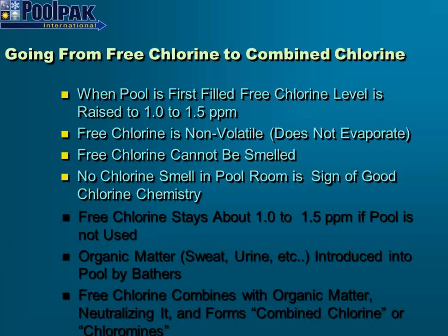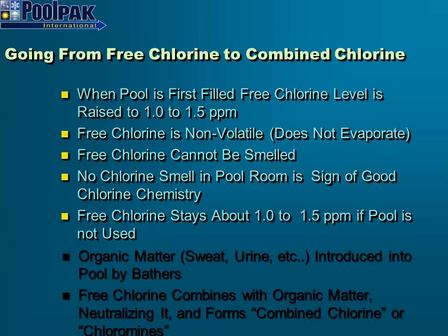We've all been in pool natatoriums. That's what the rooms are called, pool natatoriums. And we smelled little chlorine or no chlorine, and we smell very strong chlorine. If you smell chlorine, there is a problem. As long as the free chlorine stays in that 1 to 1.5 parts per million range, it will stay there if the pool is not used.